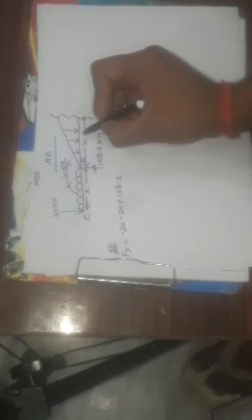Now come to the portion AD, right? When we are considering portion AD, the section will be just left of D, right? Write the equation for this portion. The shear force equation will be minus 20. It is in downward direction, so it is minus. Then the total weight of the UDL is minus 20. And then the reaction plus 158.5. And then the total weight of the UVL.